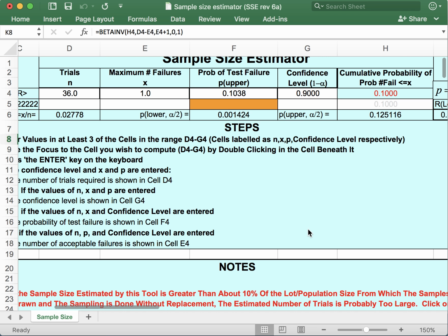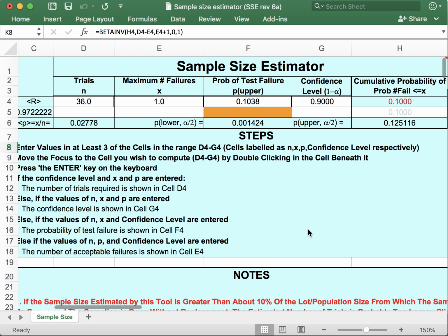And you could actually graph that reliability as a function of samples and whether the sample is a pass or a fail. And what you'd see is your reliability with 1 sample would be, of course, very low. Reliability with 2 and 3 and 4, it would grow over time. And then when you hit sample 36 and there's a failure, your reliability would jump down. And it would grow, grow, grow. And when you hit another failure, it would go down. So you could look at the reliability as a function of the number of samples being tested and whether they passed or failed. And depending on what your application is, you can make use out of that data however you see fit.